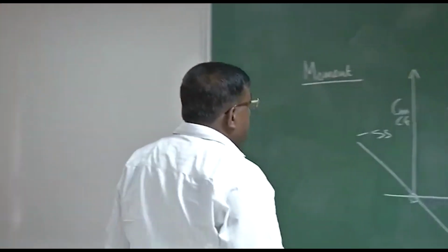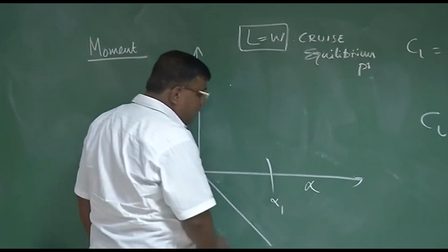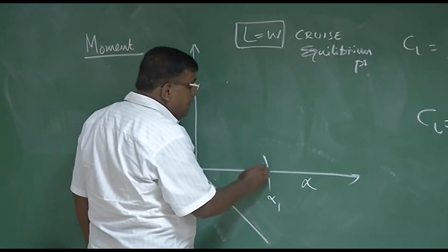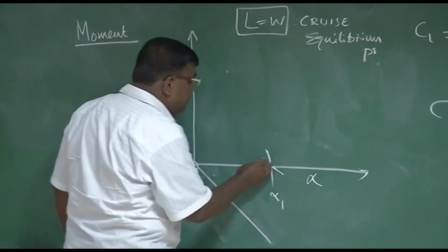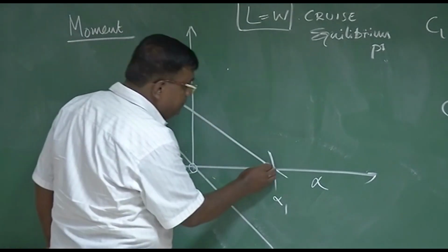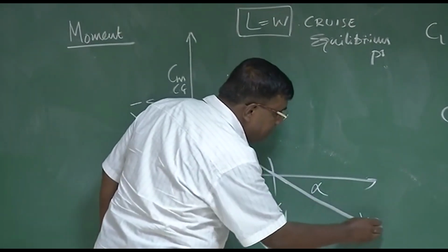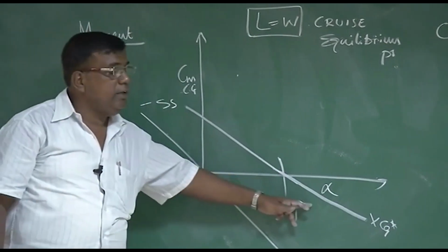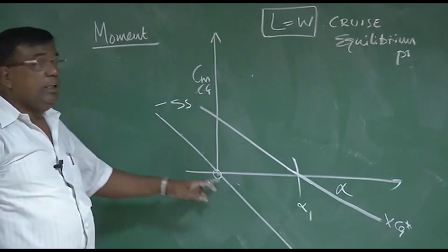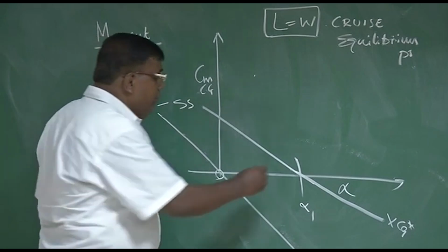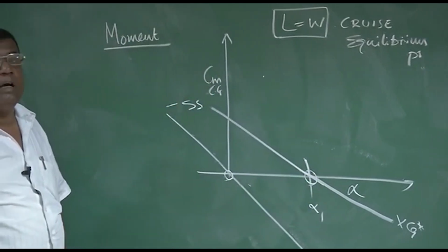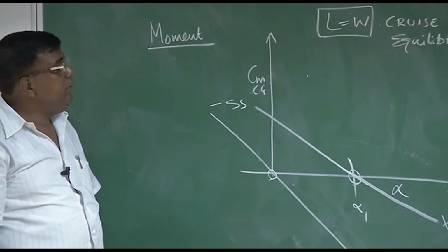And now at this alpha, if I want to fly, and I want it to be statically stable, it means the slope here should be negative. If my airplane has this sort of Cm versus alpha rather than this, then I can get a positive angle where I can fly with the appropriate speed to maintain lift equal to weight.